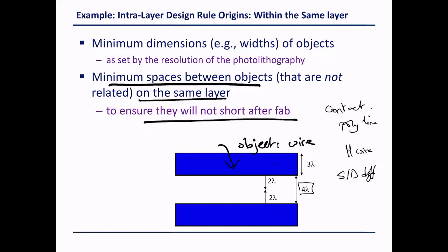But we are not bound by certain specs. These are the design rules. That's what he's telling you. He's telling you that if you are on the layer of metal 1 and you want to draw a wire, it has to have a minimum width of 3 lambda. It cannot be shorter. We didn't put it here because we're not talking about area. It cannot be closer to any other wire than 4 lambda. Before you place wire 2, if I have wire 1, you have to adhere to this rule. Okay.